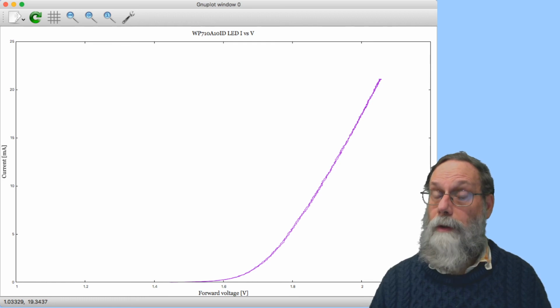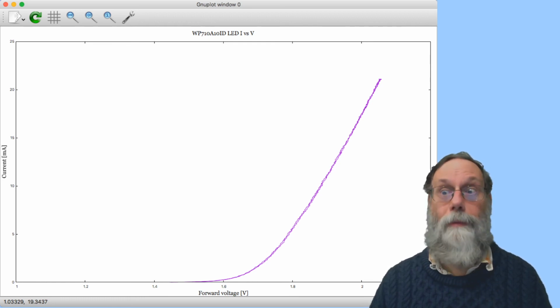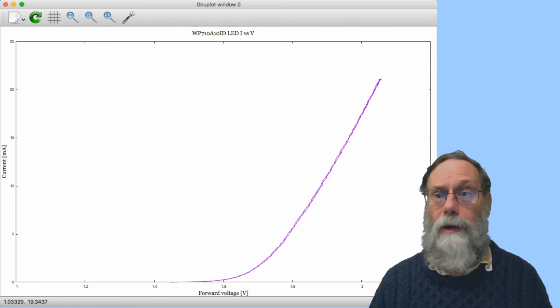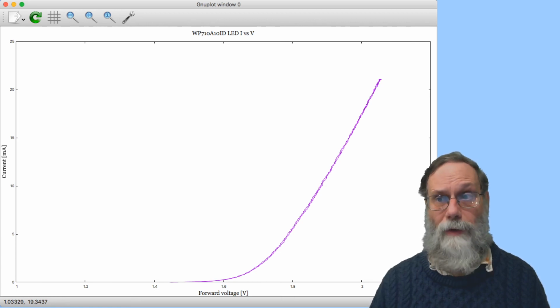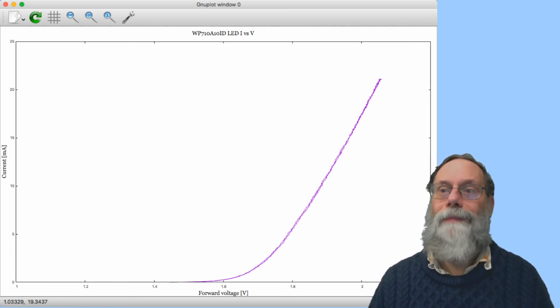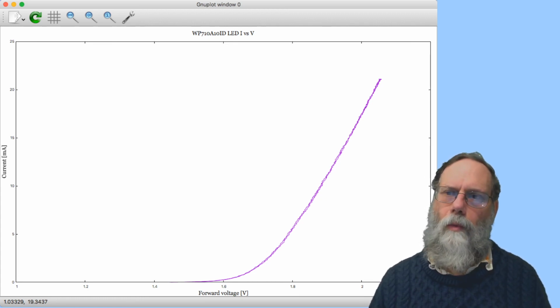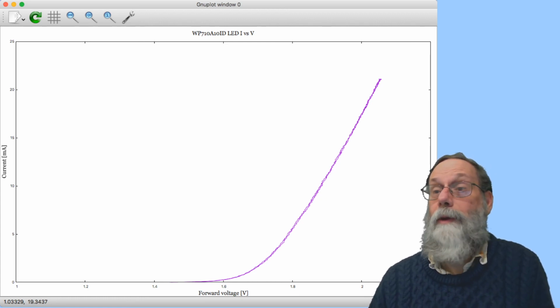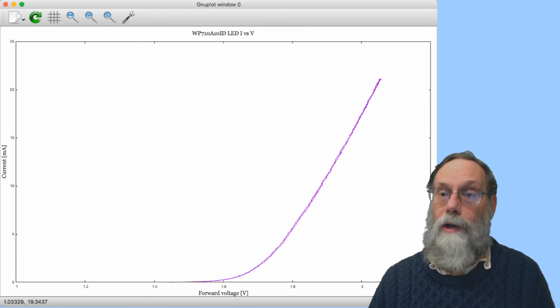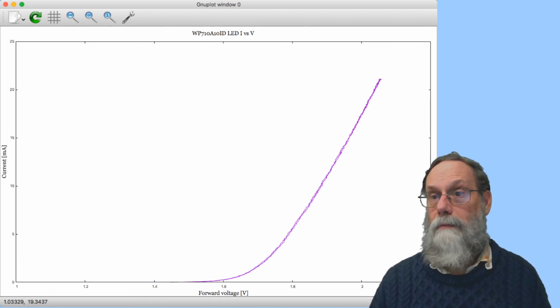We were warned that we couldn't put more than 30 milliamps into this thing, and we'd probably want to design around somewhere in the 10 to 20 milliamp range, because that seemed to be where they were giving the operating specifications. So what do we do? If we just put our 3.3 volt power supply across the diode, we're going to get some huge current.